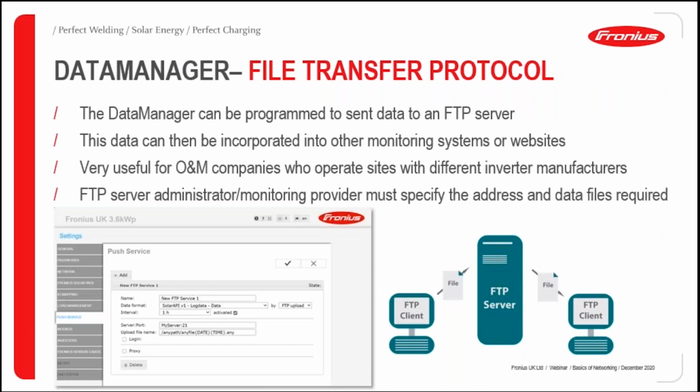The data manager has a useful function called push services, which enables FTP push to a third-party server. This means that you can incorporate your PV system's data into another monitoring system or into external websites. This is particularly useful for operations and maintenance companies who may be providing maintenance for a number of different installations with different inverter manufacturers.